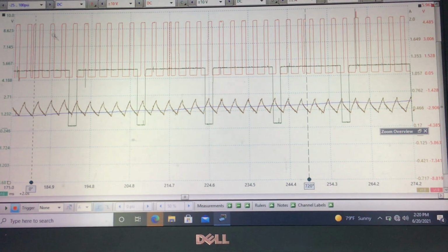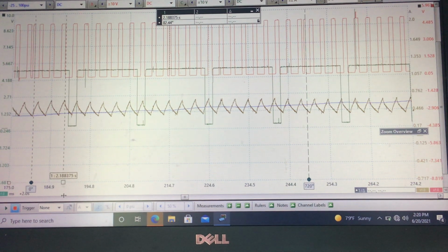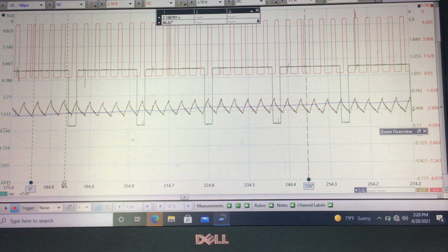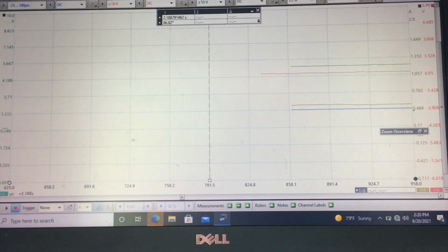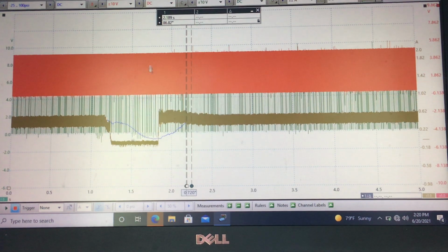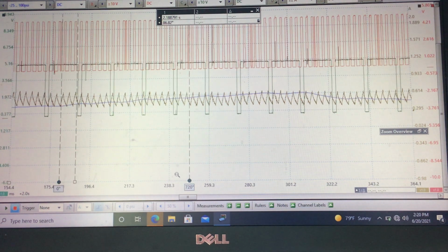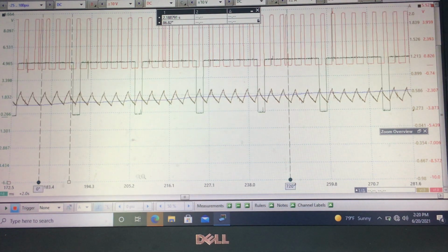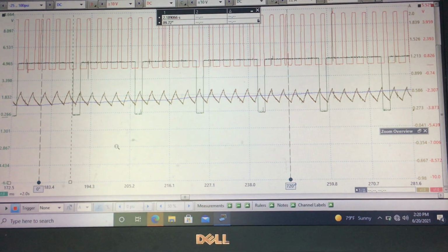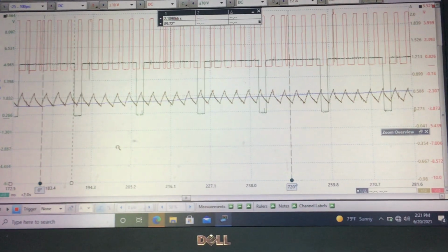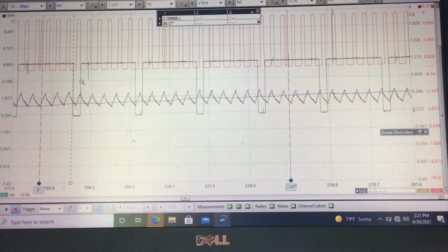Okay, that's 720 degrees of crank rotation, and let's see where we are here. We were 101 degrees. Okay, right here we are, okay, oh, my bad. Okay, we're about 89 degrees. So that's a lot less than 102 last time. So we're closer to that reference point on the crank. So this timing was advanced.